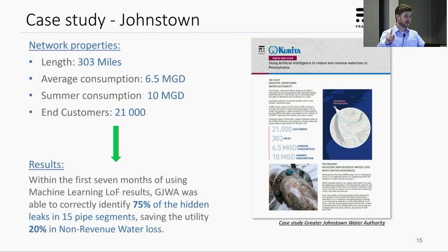But the one I wanted to touch on, which I think is more important down here, is non-revenue water loss and leak detection. We are not a leak detection company. Our service is not called leak detection. We're not out there detecting leaks, but what we found is that high likelihood of failure pipes usually mean that pipe's leaking already, especially in places where you're not using PVC. Now, down here, that obviously may be different, but the idea is that a high likelihood of failure pipe is going to correlate to most likely a high leaking pipe.